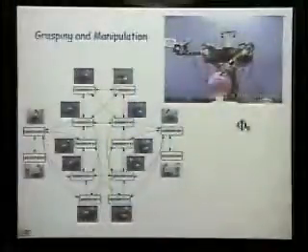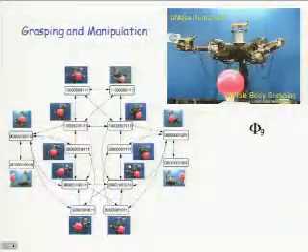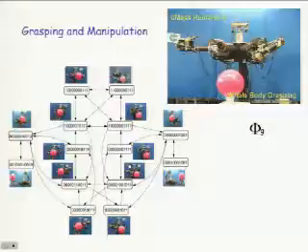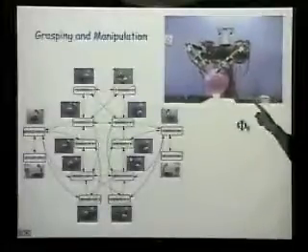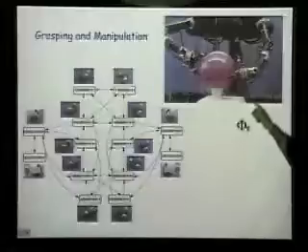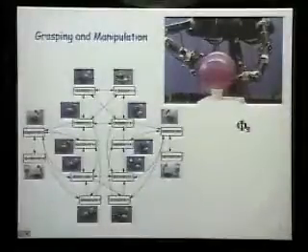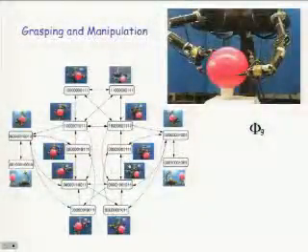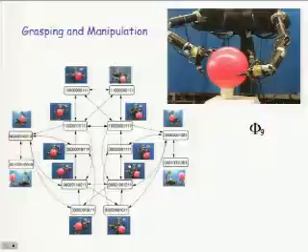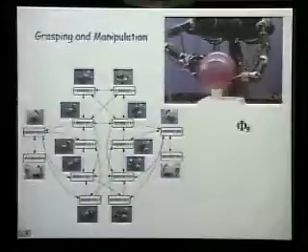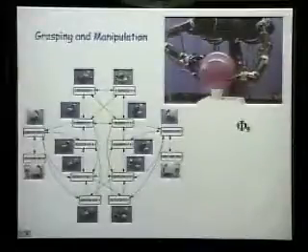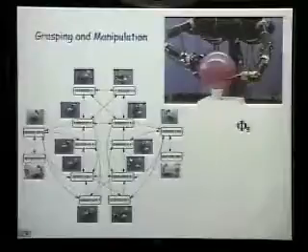All right, now my robot should run. Okay, now I'm going to leap into a new domain. This is grasping and manipulation. This is our platform Dexter that you see there. Right now what it's doing is running a schema that we call the grasping schema. The grasping schema applies little contact sensors at the fingertips of those hands to the object to try to figure out where all the forces are in the bimanual grasp. And there's a particularly compelling signature of a stable grasp. It's looking for that, and it's doing a gradient descent on a controller we designed to do that. Right there, it'll grasp it when it's finally happy with it.